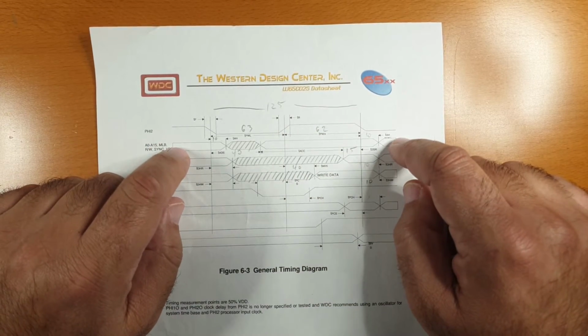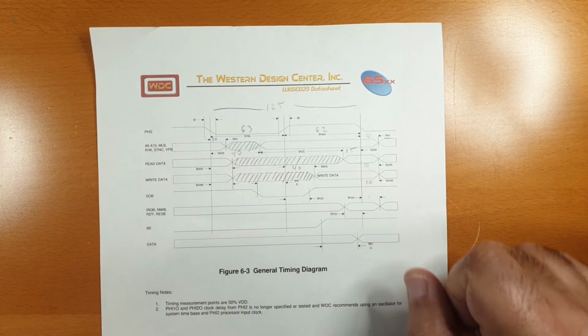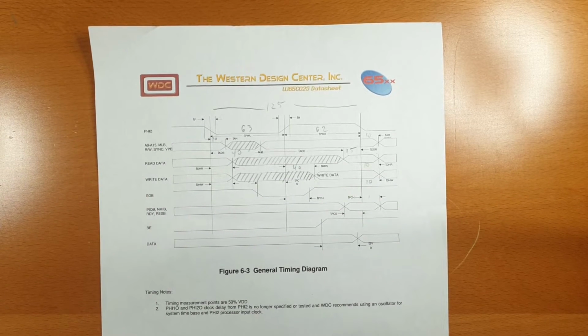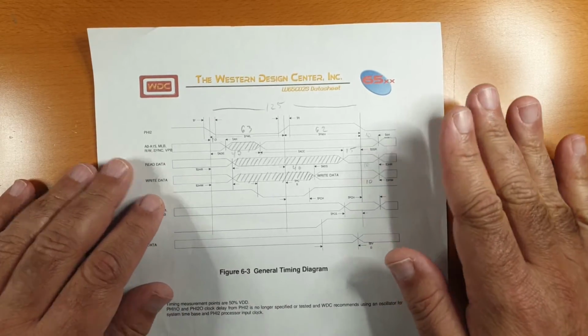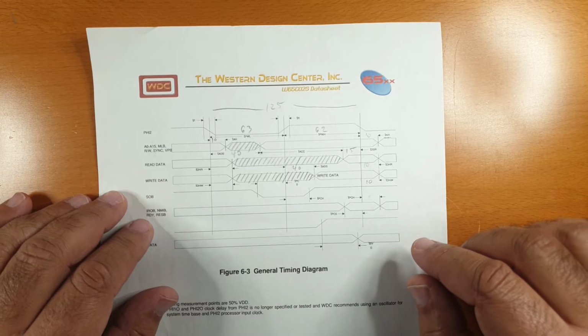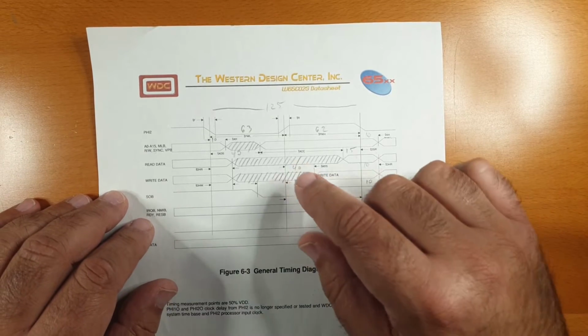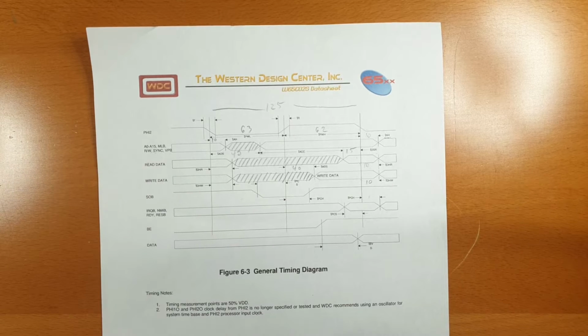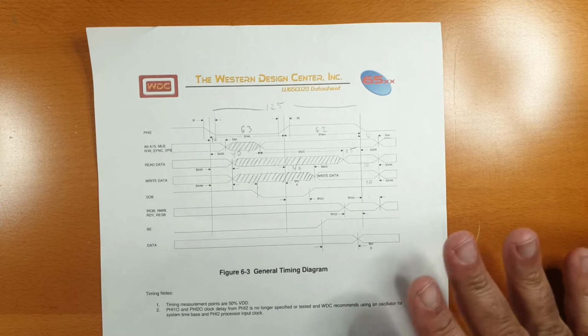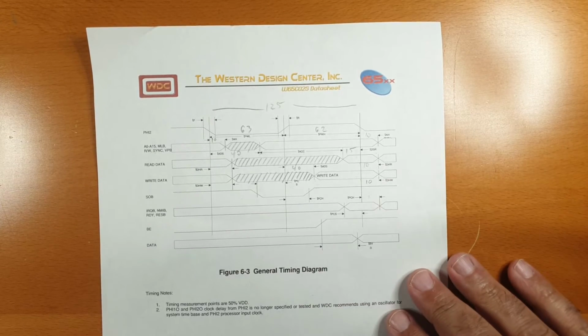Now, it is debatable whether the 6502 updates anything on the rising edge of the clock, but I'm not bound to their design, so we are updating registers on the rising edge of the clock, despite the fact that that's a different design than the original 6502. In the future, I may revisit this decision, but not before all the opcodes are implemented. With that out of the way, let's do a sample opcode analysis.